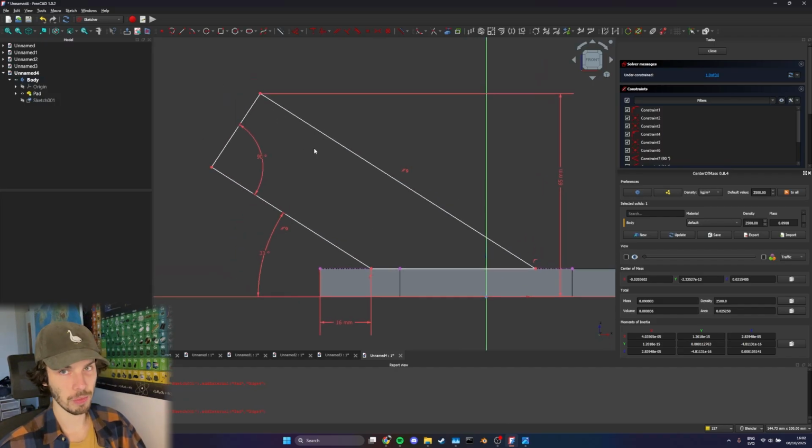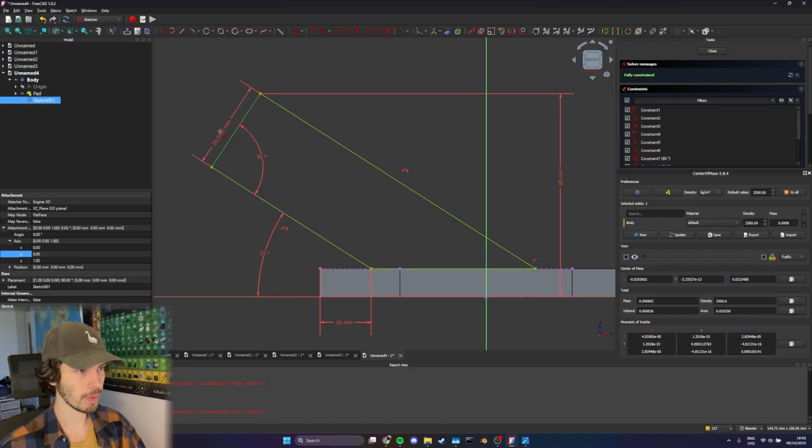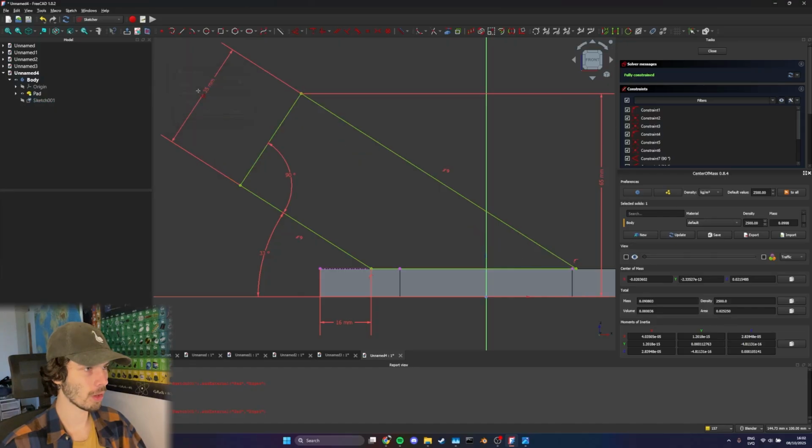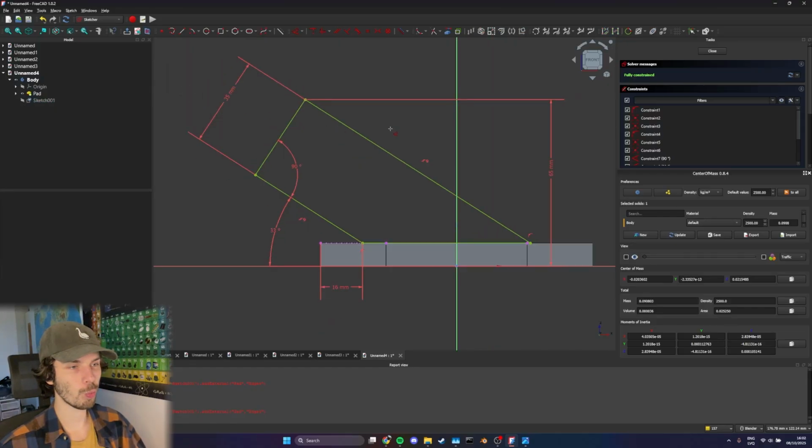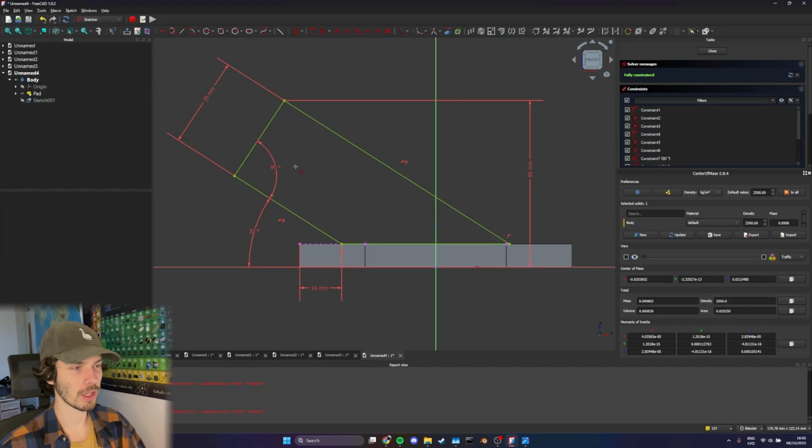As we can see from the drawing, the pipe's diameter is 35 millimeters, so we can press on the dimension tool, drag it out, and type in 35 for the diameter. Now we can see the whole thing has lit up green, and we're ready to leave.